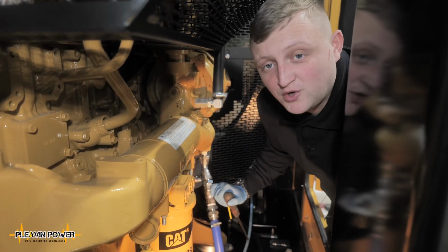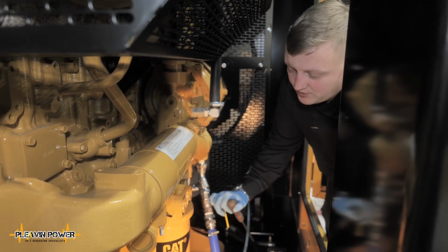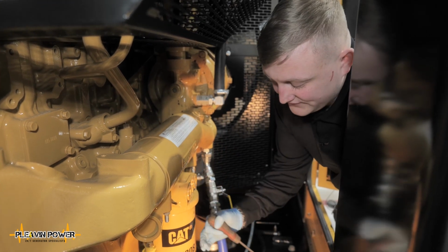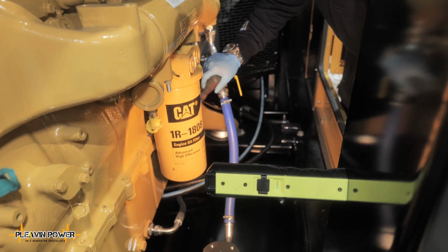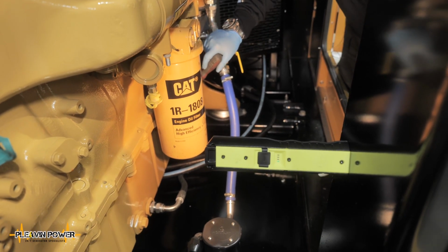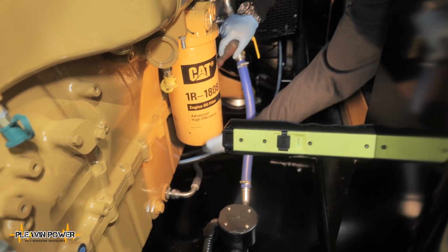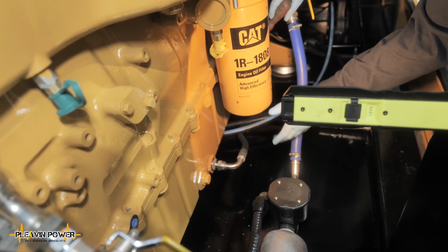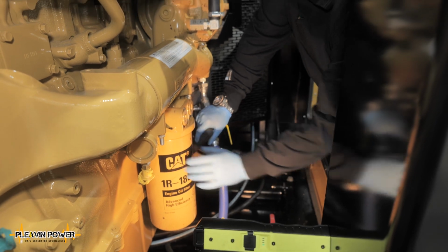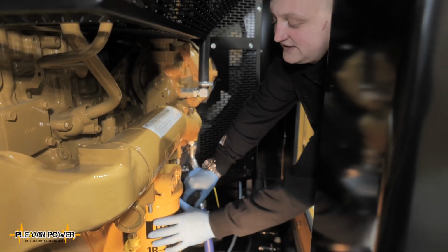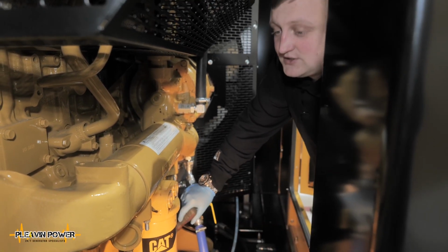Okay guys, so you join me on the opposite side of the engine in this scenario, and what we're looking at is the oil filter. This oil filter should be changed initially at 250 running hours of the engine from new, and then at every 500 hours of operation. They should be changed at the same time that oil is changed to make sure that the new oil is filtered and any contamination or debris that have entered the engine crankcase itself is filtered out in a safe manner. This filter needs to be changed at every 500 hours mandatory to ensure that the engine